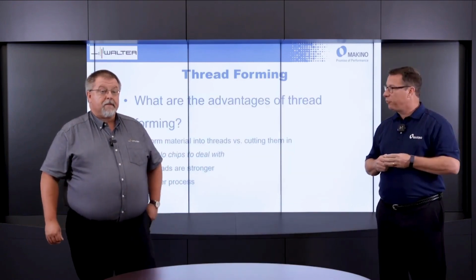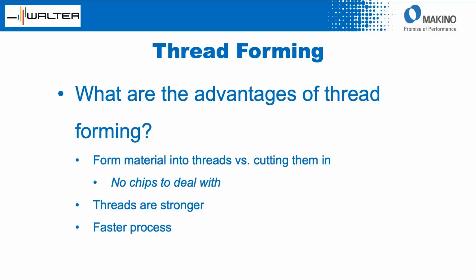So, advantages of thread forming, Brian? Like I just touched on, the first thing is that there are no chips to deal with. All right. So we're not going to have bird nesting. We're not going to be filling up chip carts. And I've been in a lot of situations where people have cut their hands getting those chips off. That's gone. We are forming these threads, and by cold forming, we're going to compress that material and create a stronger thread. And in the process, it's also a little quicker.